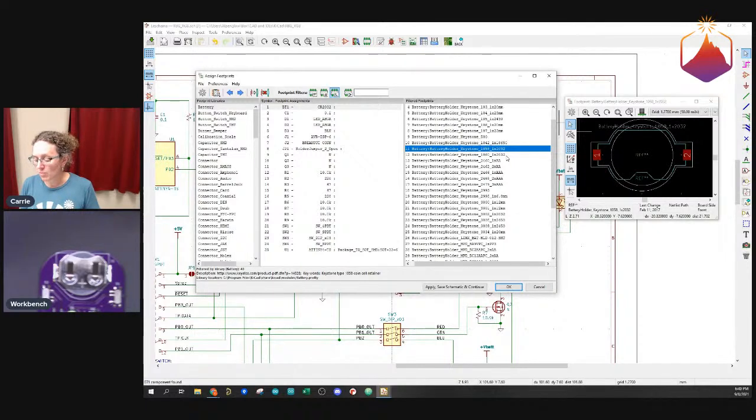And we had a problem where just the pressure of having the battery in there, because they're little spring-loaded contacts, was popping the holders off of the board. The solder joints were failing.